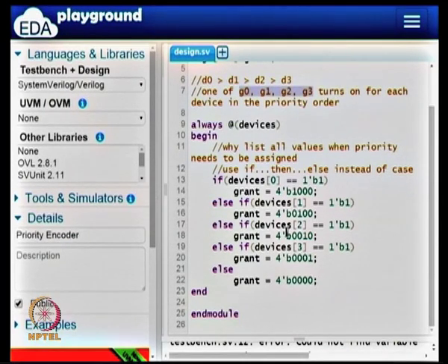This is using an always block. The previous one also used an always block. However, even within the always block, which kind of statement you pick, there is beauty in the code here. This is much more natural, and in terms of hardware, this is much easier to translate, and this is less error prone, because this explicitly says these are the bits I am looking at, and that is all. If you are to type even let us say 2 power 6 lines, somewhere you may make a mistake, so that will not happen here. So this is a very nice style for writing this priority encoder.